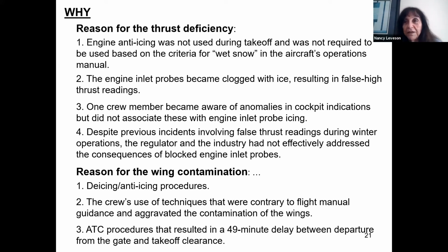We are looking at a behavior of the pilot that was not optimal here, but we didn't say he failed. We make more of a factual statement. We said he became aware of the anomalies, but didn't associate these with engine inlet probe icing.